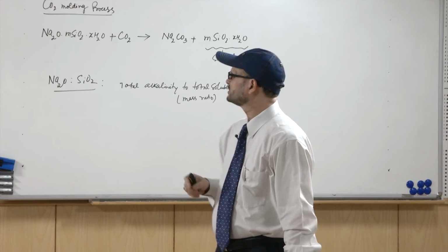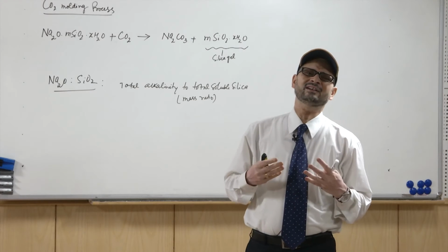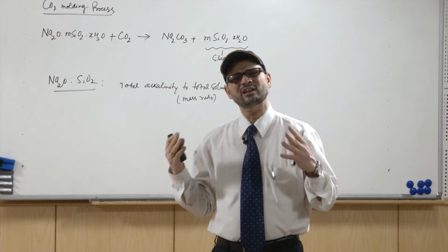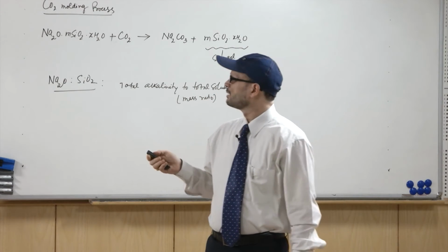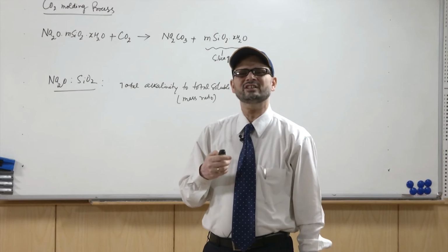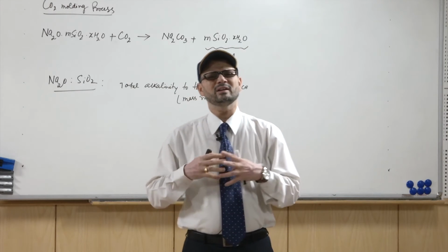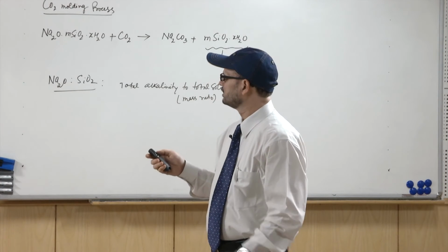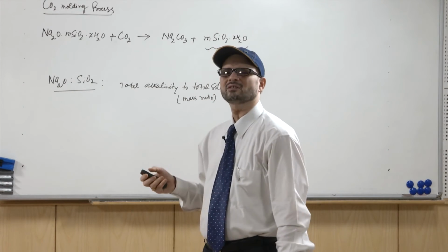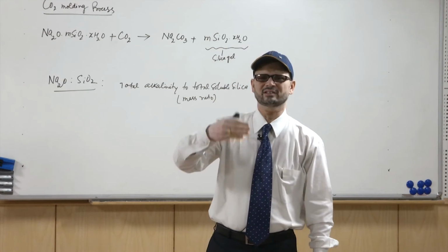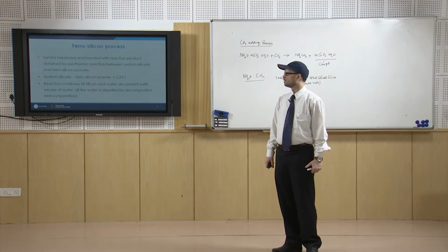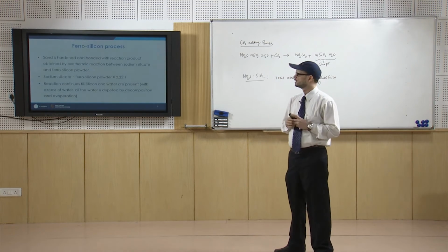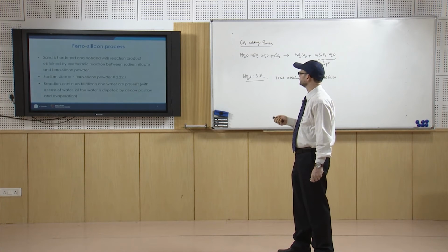So, they are basically used for different kinds of castings, mostly for small, medium and large scale castings, this type of processes are used in industries. All the automobile parts are basically manufactured nowadays using these carbon dioxide moulding processes if they use the inorganic binders. Now, the next process where the sodium silicate binder is used is the ferro-silicon process.